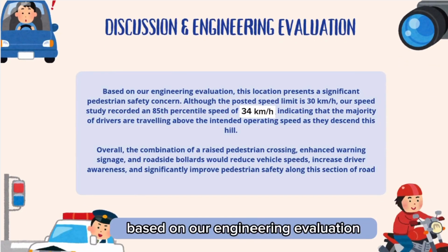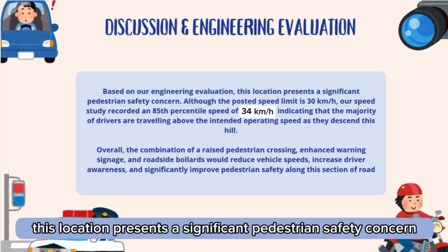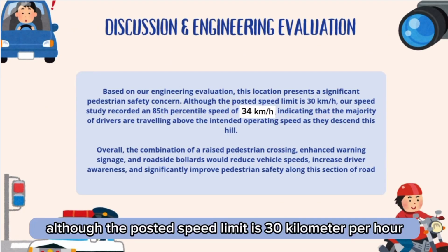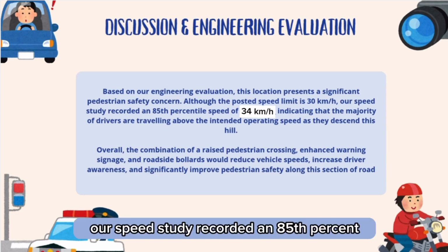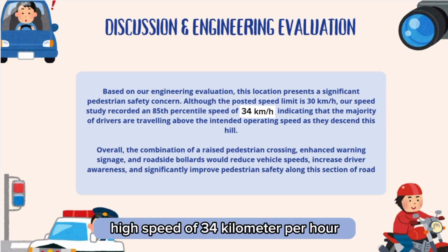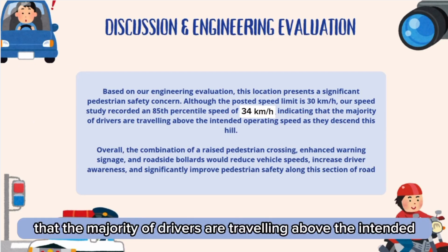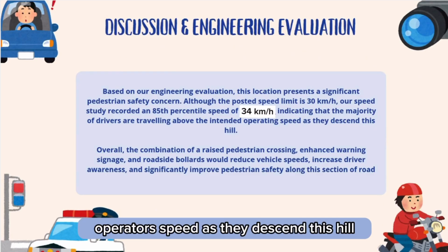Based on our engineering evaluation, this location presents a significant pedestrian safety concern. Although the posted speed limit is 30 km per hour, our speed study recorded an 85th percentile speed of 34 km per hour, indicating that the majority of drivers are traveling above the intended operating speed as they descend this